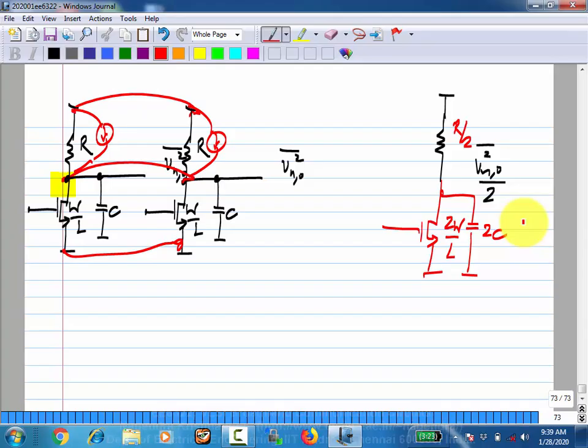So now what is the price that you pay when you do this? Area is fine, but power dissipation is the important thing. Of course, the area also increases. So you're not getting something for free. You will have half the noise variance or noise spectral density at twice the power. So power dissipation will always be proportional to the signal to noise ratio. This is again some fundamental relationship.